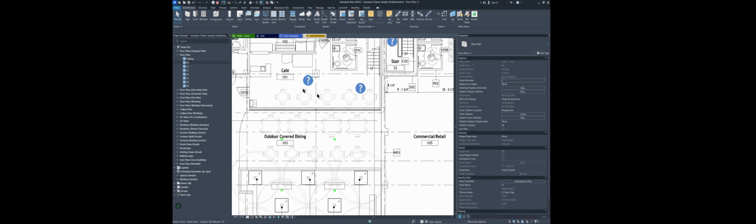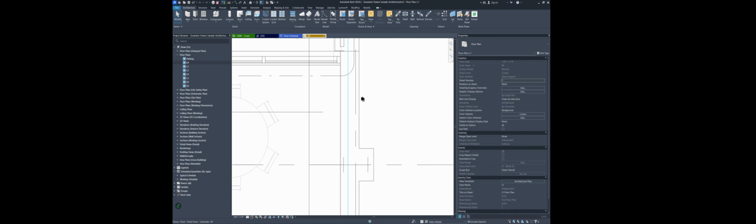The other thing is you mentioned families that you reuse, right? So like this table and chair, if I plan to use this in other places, I want to load it from the family. But you also have this one-time use family. I call it, it's like when you have single-use plastic cups, knives and forks or whatever. You have this single-use family called model in place, where I just need a little weird thing to be drawn here.